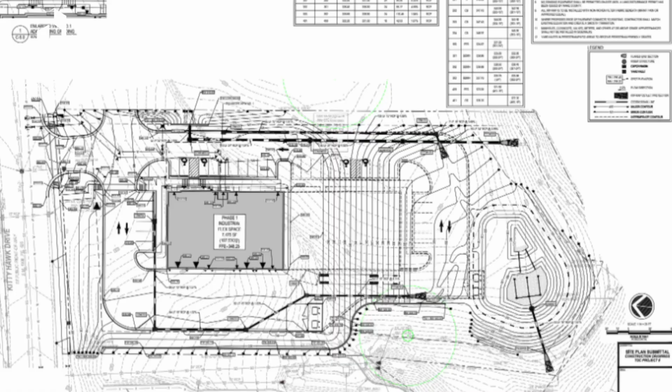This construction drawing shows how stormwater will be captured and routed through the site. The stormwater detention or retention device will be the water's ultimate destination, but in order to get it there, a civil engineer needs to come up with a plan using the planned grades and stormwater infrastructure to avoid water and erosion on the site and nearby properties.